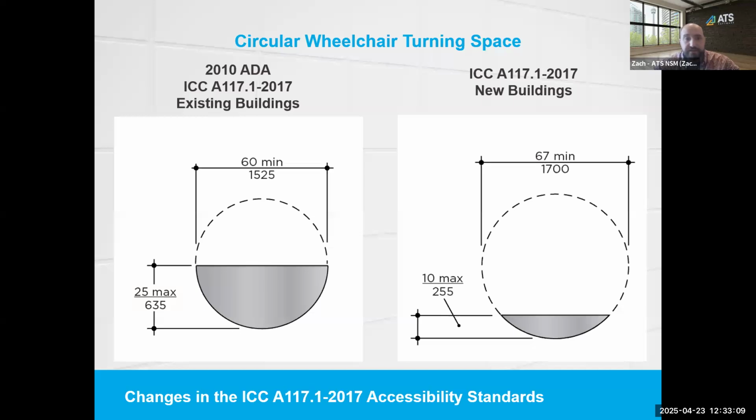And then into some of the details that we covered here. So we talked about overlapping a little bit in regards to a counter. There's a question coming in regarding overlap of the turning circle and the door swing allowed. And if so, is there a max dimension there? There are some dimensions, and we'll get into that a little bit later, that allow door swing to overlap and some that do not. So it varies. A door swing cannot overlap the clear floor space at a toilet. That's an example of the impact of door swing.